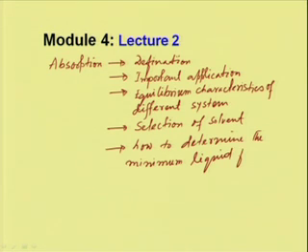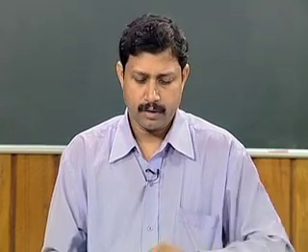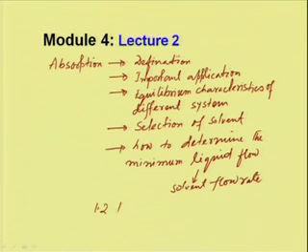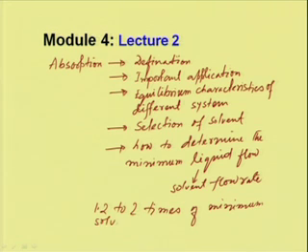liquid or solvent, in other words solvent flow rate, and then we gave an example of how to determine the minimum liquid flow rate, and in general the solvent circulation or flow rate is about 1.2 to 2 times of the minimum solvent rate.